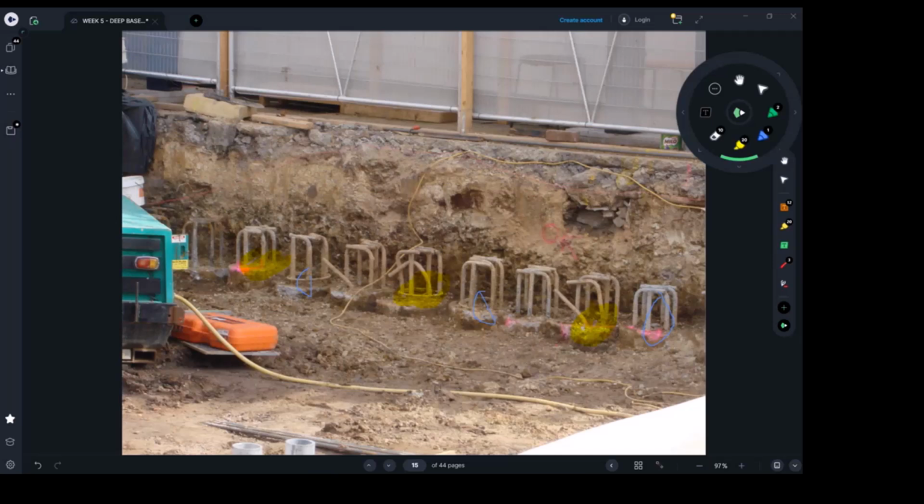Yeah, then maybe after 3 or 4 days, they're gonna come and do the yellow ones. And same thing, they're gonna use maybe the CFA method. They're gonna pour the concrete, place the bars, and then after a week, they're gonna do the green ones. They're gonna do this one and this one and this one. We call this hit and miss. So we do them at different stages.